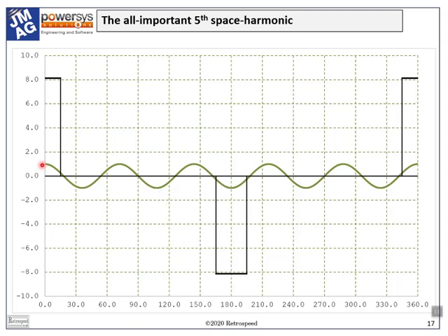The normal fifth harmonic coefficient for this waveform would be 0.1230 if the rectangular pulse had a peak value of 1. But the reciprocal of that is 8.13, which explains the scale. Since the fifth is the working harmonic, it's natural to normalize everything to that harmonic.